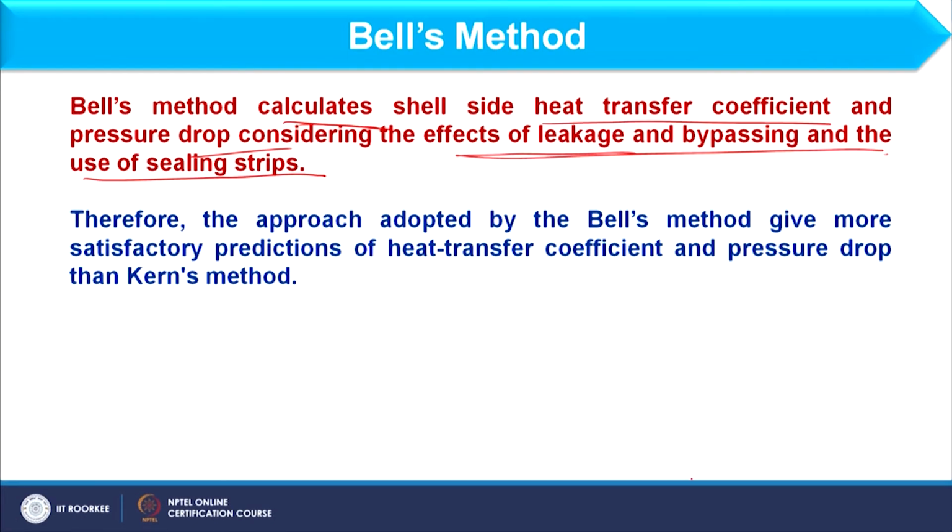If I am comparing this method with Kern's method, obviously Bell's method gives more satisfactory results in comparison to Kern's method, but it takes more time in designing the shell and tube heat exchanger. But if we require a more accurate design, we should choose Bell's method, right.